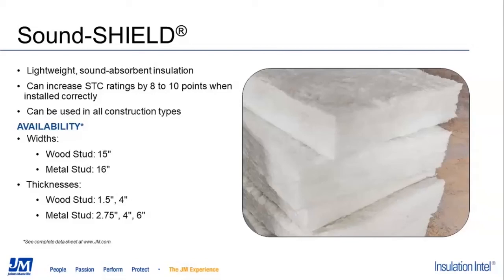And usually for interior wall applications where R value is not important, but sound control is, or even between floor applications. Sound Shield is available really in limited sizes and are typically thinner products like 1.5 inch shown here under wood stud and 2.75 inch for metal stud. But we also have 4 inch and 6 inch. So unfaced fiberglass and Sound Shields are designed for residential and commercial applications with smaller frame cavity widths.